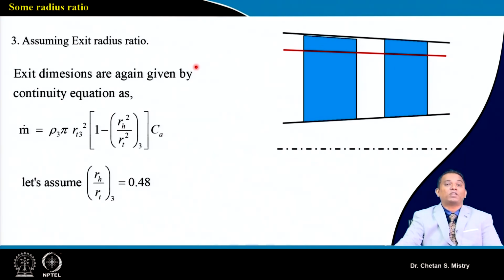Okay, suppose that's your case. In the same way for the HP compressor, downstream we have the combustion chamber. So the person doing the design for the combustion chamber will say, this is the dimension I am expecting from the last stage of the HP compressor. Under that condition, we can go with this kind of radius ratio assumption. You can even go with constant mean diameter.